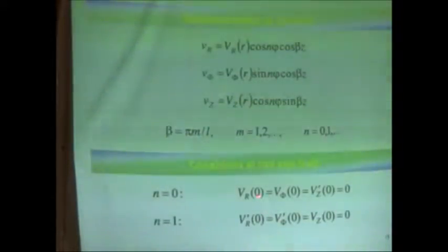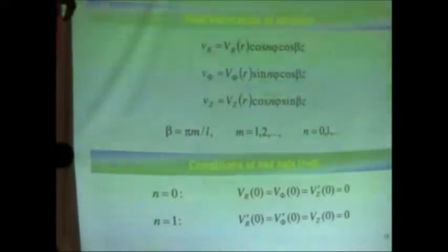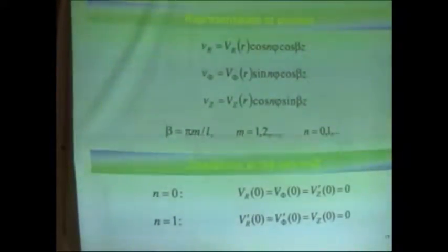These are the conditions for the symmetric buckling mode and for the bending buckling mode. Now our linearized boundary value problem is complete, and we can study the stability of our rod for a given material model.